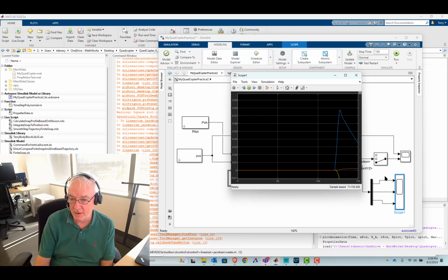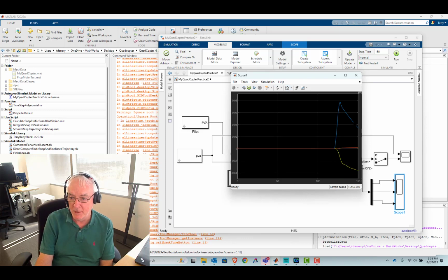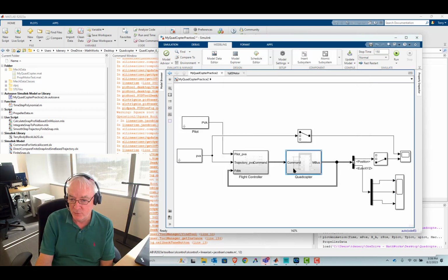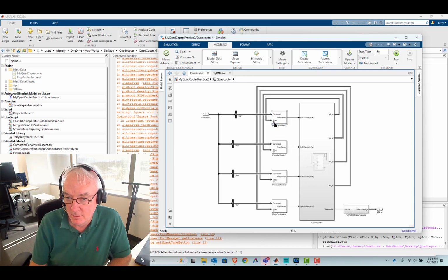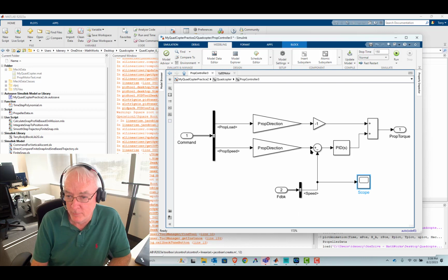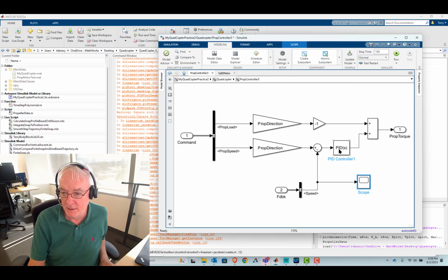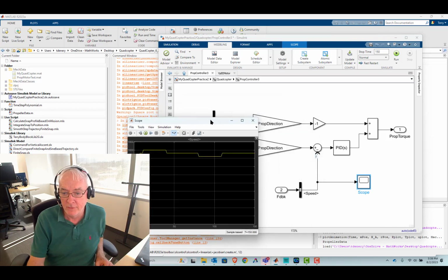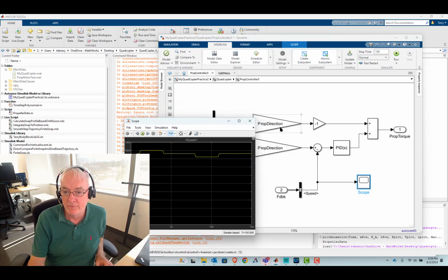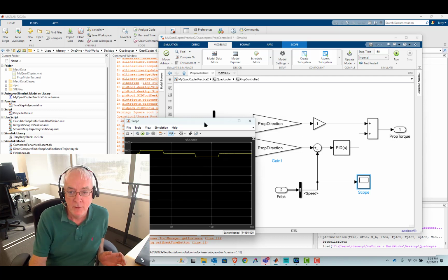So anyways, let's continue with this. Let me just validate a little bit my suspicions that there's a problem with the controls. We'll go into the motor controls that are on the plant side. We got that PID right there. I put a scope on the angular velocity, and that's the job of the feed forward and feedback through the PID to hit the command, and it looks beautiful.